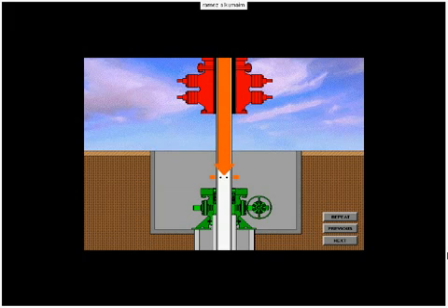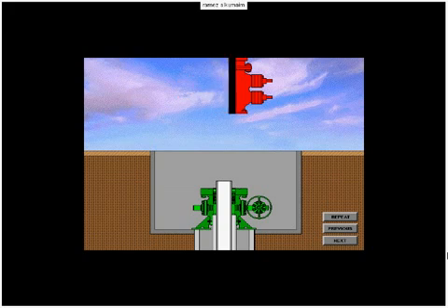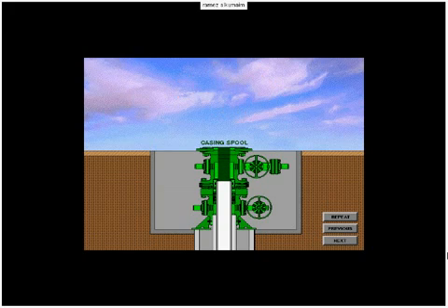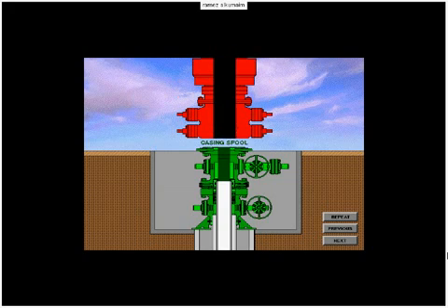Holes are cut in the casing to allow the drilling fluids to drain out of the casing riser. When the casing is drained, a rough cut is made and the top of the casing riser is removed. The BOP system is removed. The casing spool with a crossover seal is installed. The BOP system is nippled up, and preparation is made to drill out for the production casing string.